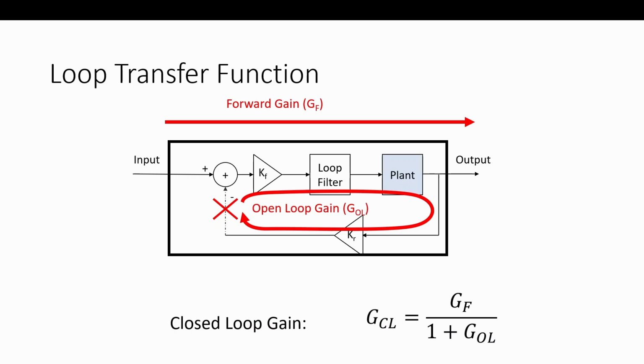And ultimately on this page, you're seeing this relationship, which is great because it holds everywhere, of the closed loop gain. Closed loop gain is going to give us the two-port network that this complicated internal thing ends up being. It's just a simple two-port filter as a closed loop gain. And it's going to be the forward gain over 1 plus the open loop gain. That denominator is called the characteristic equation. Come across that, characterizing the whole loop. So if you're successful in getting the open loop gain, then you can, from any input to any output, determine the closed loop gain, which is great.